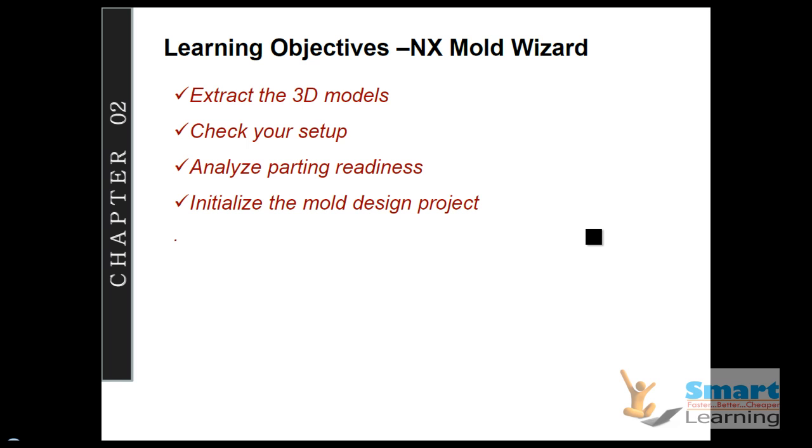In this session, we are going to discuss the NX mold design principles, in which we look into extracting the 3D model. That means how you can prepare your 3D model for doing the mold design, how to do the checkup for your setup, how to analyze parting readiness, and finally we'll look into the initialization process for mold design. That means how to configure your shrinkage, your unit system, and so on. That we will look at during our live demonstration.